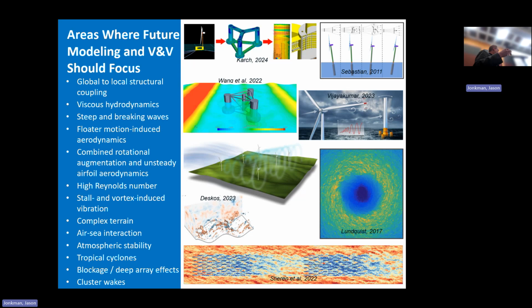Atmospheric stability. All the IEC standards are based on neutral conditions, and we know in reality that there are stable and unstable conditions, and these have a big impact on wind farm performance. And so including that into the design process is quite important.